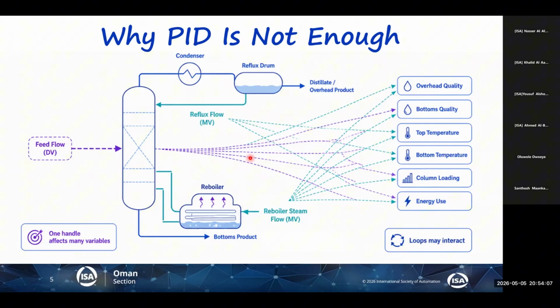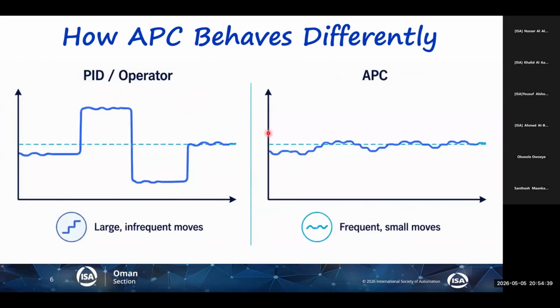Omar said yesterday, yes, I would recommend advanced process control here. Imagine you have more controllers, which is usually the case, which interact. Because look at this bottoms product. If it's going to another column, that column will be affected by this flow, its temperature, its flow increment. The difference when advanced process control is on is clearly seen for us.